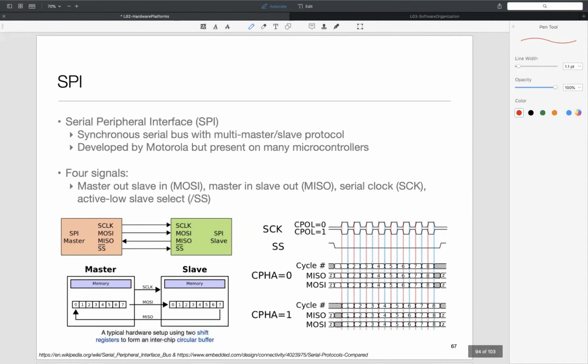The final interface you will encounter quite a bit for very simple stuff is the SPI interface. And SPI is really, really super simple. There is a clock and there are data lines for input and output respectively. And then there is a separate slave select signal. So kind of the idea is that you literally toggle the clock, and then every clock tick you send a different bit.